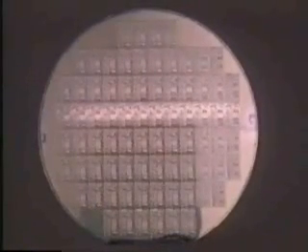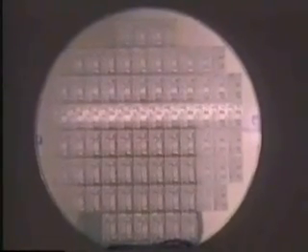It all begins with the growth of pure semiconductor crystals, usually made of silicon, an element found in the Earth's crust. Lightly doped silicon crystals are sliced into wafers, which are cleaned and polished on one side. On this polished silicon surface, many integrated circuits or chips are then fabricated. Each one of these chips is a complete circuit, consisting of many thousands of transistors and other electrical components.